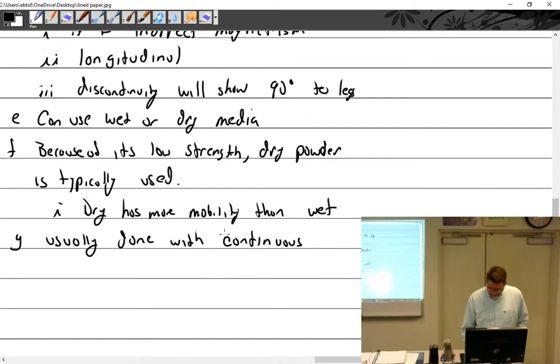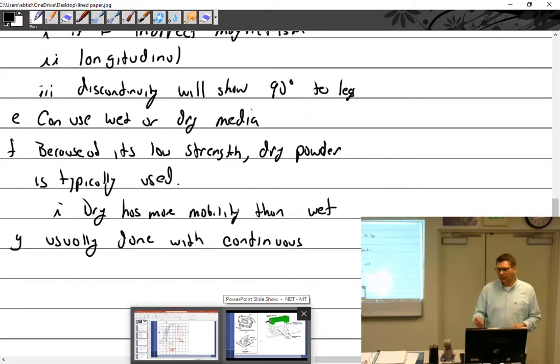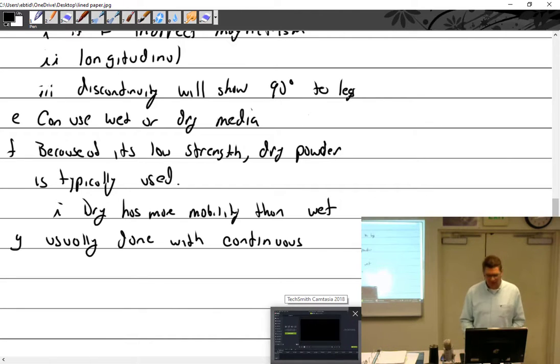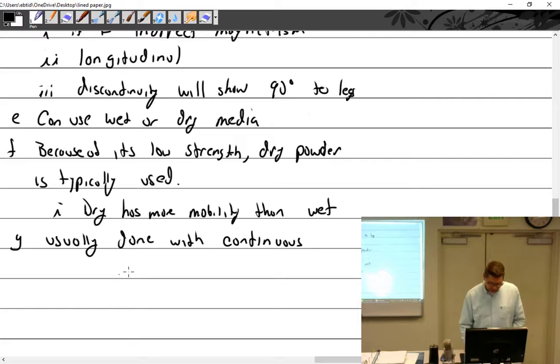All right, now so I gave you a demonstration. You put the yoke on there, energize it. You have a little blower, and you blow the particles on there, and you can actually get another blower and blow the little particles around that are already on there without having to add a bunch more.